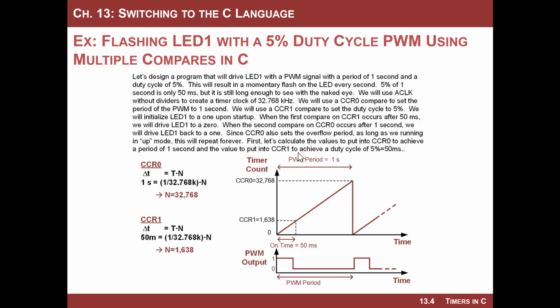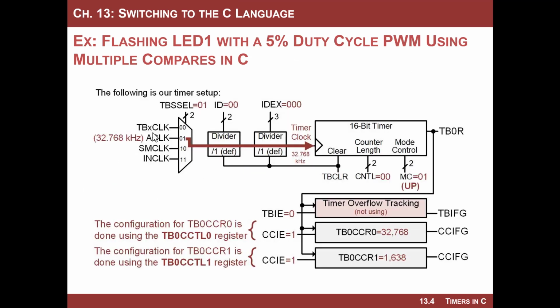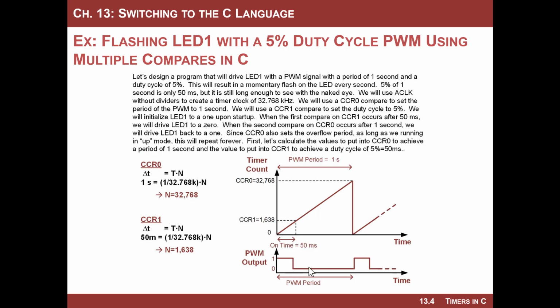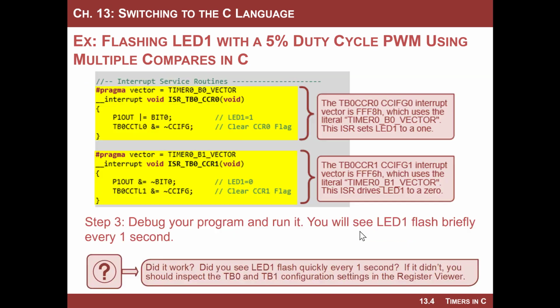Holy cow, you did it. Think about what you're doing right now. You just created a pulse width modulated signal. You set up a timer. You had two totally separate but related interrupt service routines that were run to generate a signal that you used to flash an LED. That was a lot of stuff going on. So congratulations, that's awesome. And that's it.